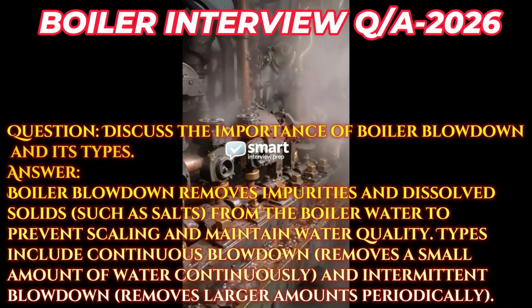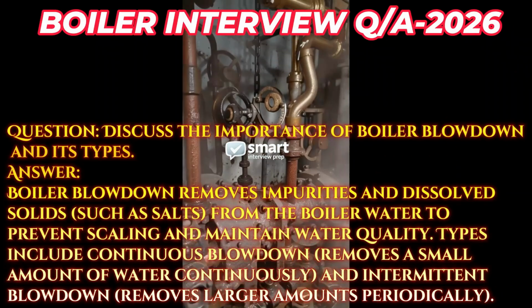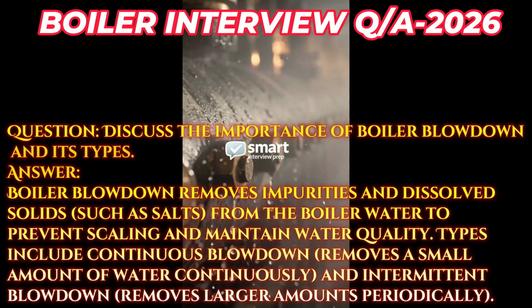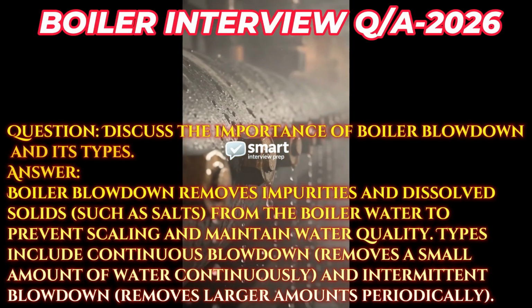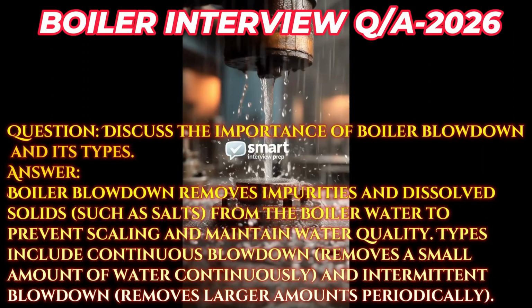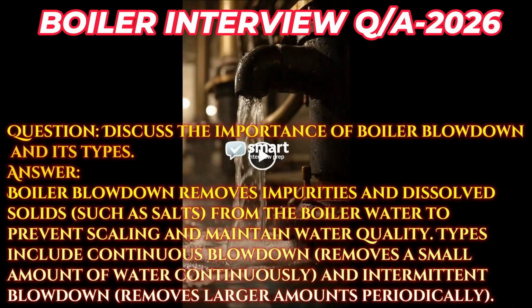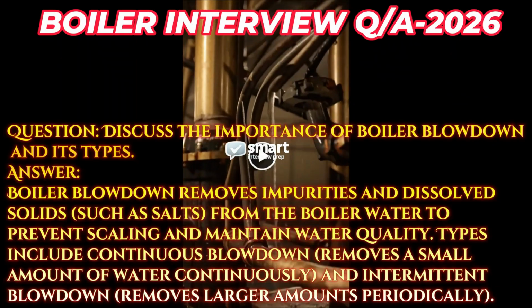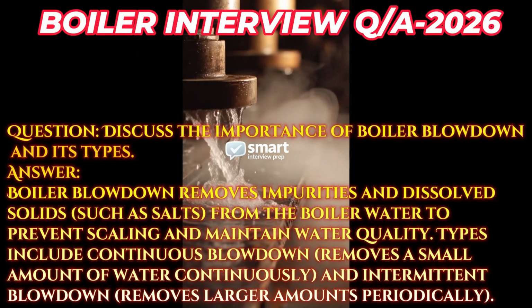Question. Discuss the importance of boiler blowdown and its types. Answer. Boiler blowdown removes impurities and dissolved solids, such as salts, from the boiler water to prevent scaling and maintain water quality. Types include continuous blowdown, removes a small amount of water continuously, and intermittent blowdown, removes larger amounts periodically.